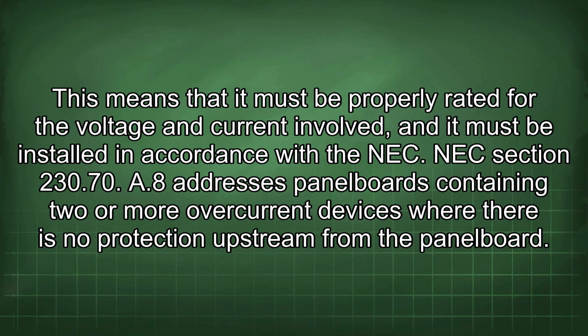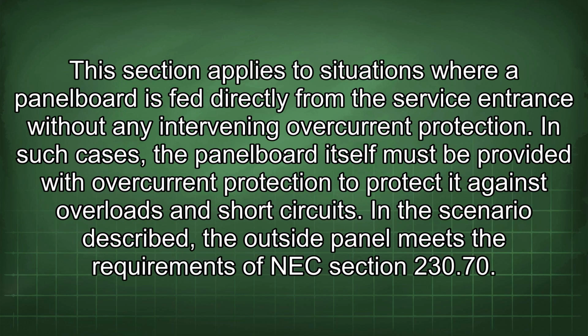This means that it must be properly rated for the voltage and current involved, and it must be installed in accordance with the NEC. NEC section 230.70(A)(8) addresses panelboards containing two or more overcurrent devices where there is no protection upstream from the panelboard. This section applies to situations where a panelboard is fed directly from the service entrance without any intervening overcurrent protection. In such cases, the panelboard itself must be provided with overcurrent protection to protect it against overloads and